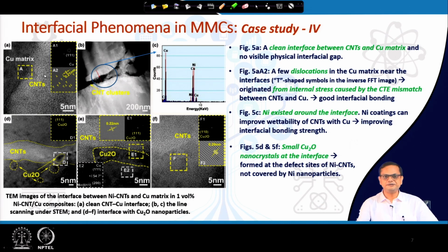I hope you understand this point, right, that the dislocations are getting generated at the interface. That means at the interface there is some residual stress, and residual stress can get generated only when it does not get released. Okay. That is why the interface is quite adherent, and because of this adherence the residual stress is basically remaining there, and that leads to generation of such dislocations.